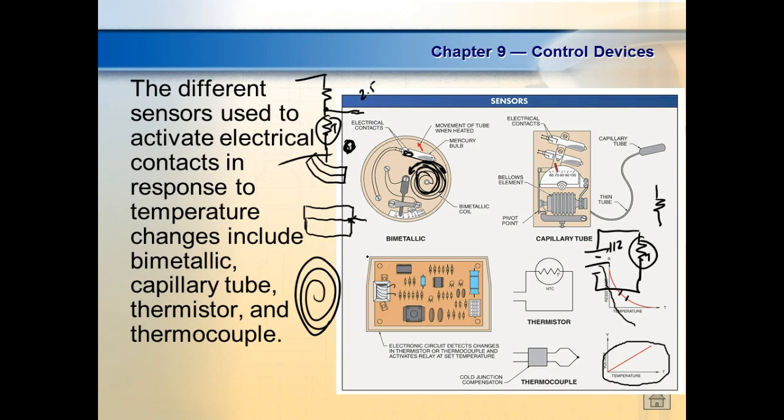Well, a Wheatstone bridge, which would take more, I couldn't do it with this arrangement. We would put it inside what we call a Wheatstone bridge, and this would allow us to set a 0. So what we would do is this would be my thermistor, and this right here would be a rheostat. And what I could do is adjust this.